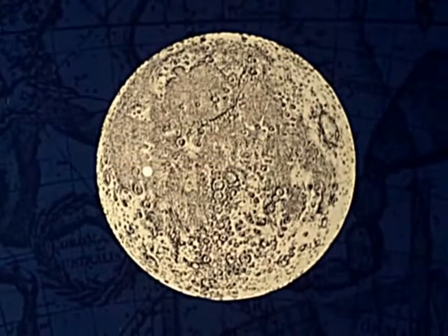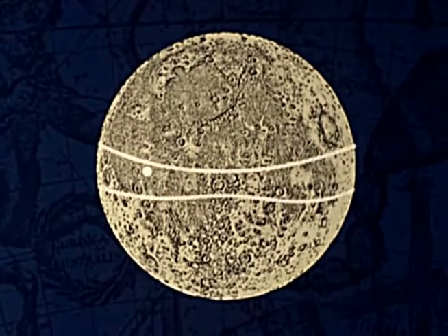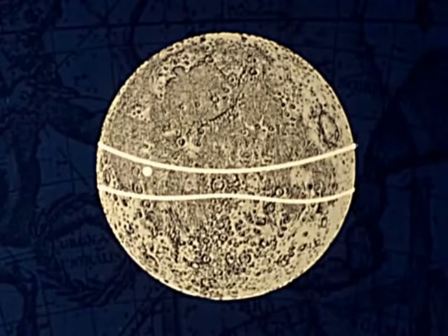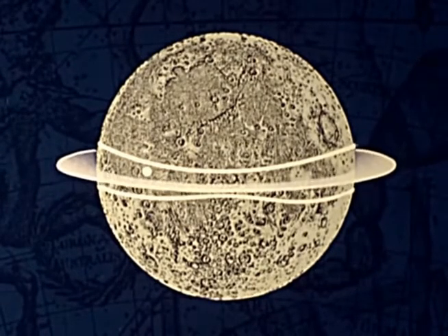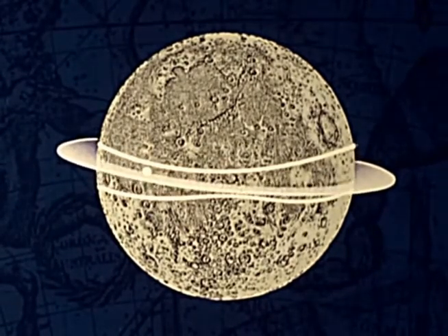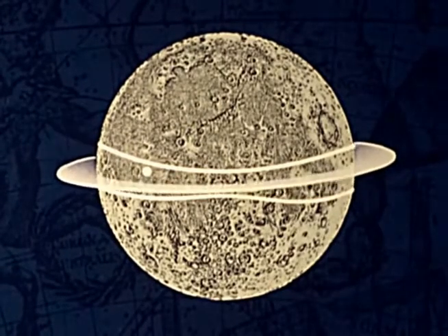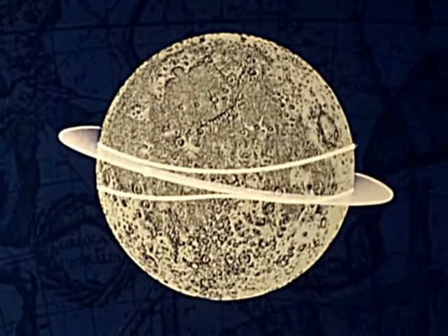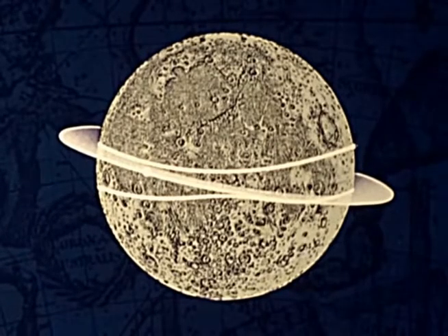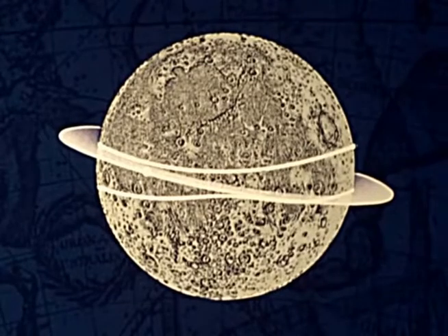The performance limitations of the spacecraft determine the latitudinal boundaries of the accessible landing area for any given day. The spacecraft, as it enters lunar orbit, must make a plane change so that its orbit plane contains the landing site. The amount of plane change it can make, directly related to the amount of propellant it can carry, is what limits the range of latitudes. This area, as determined by a combination of spacecraft performance and geometric constraints, is centered around the trace of the Moon orbit plane.